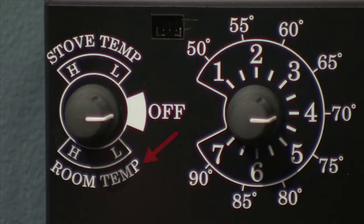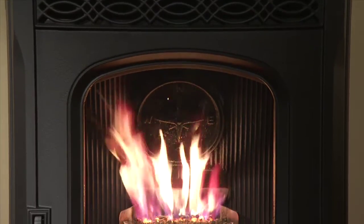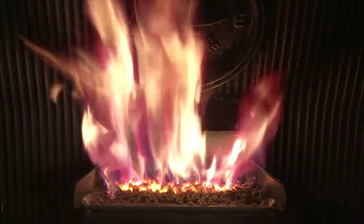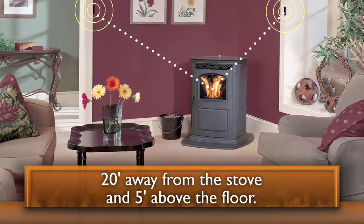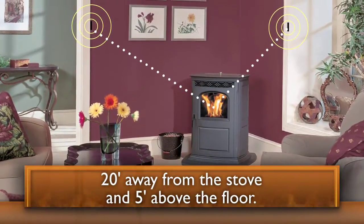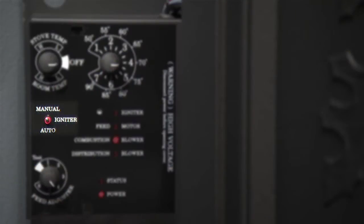Room temperature mode uses a sensor to monitor the air temperature in the room. Based on your desired setting, the stove will automatically adjust its burn rate to maintain a constant comfort level within 1 degree of your set temperature. The optimal distance for the room sensor is up to 20 feet away from the stove and 5 feet above the floor. With either operating mode, you can choose to light your stove automatically or manually.